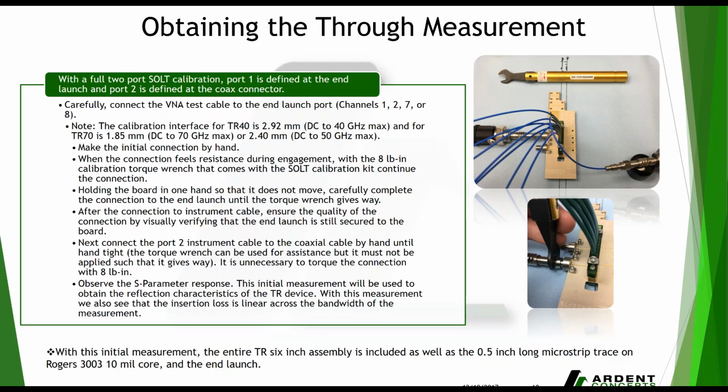With that being said, it's essential that you align those edge launch connectors very carefully, because with misalignment, there's signal degradation. What that really points to is an important note: something like the TR multi-coax connector offers fine alignment with dowel pins, and you won't have any issues like that. So eliminating the need for edge launch connectors or individual connectors that have to be aligned isn't a problem with something like the TR multi-coax. That's something to note and something to think about in your designs.